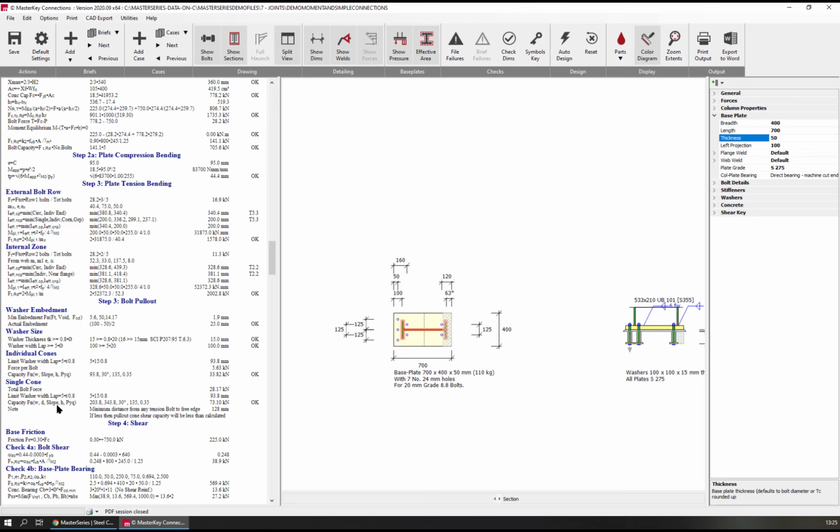Shear cones are an old-fashioned methodology, and they're really used when we have no top steel. So I'm going to say I want to use a punching shear perimeter, and it's still working on cones, and that's because there is no top steel.